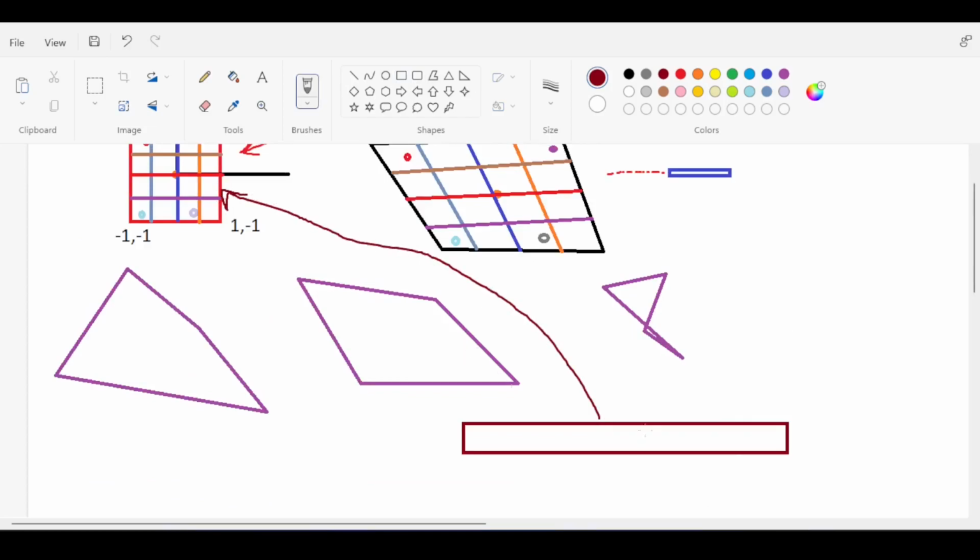Heavily modifying means that in one case you would just multiply by 2, for example. In another case you would divide by 5. This is a huge aspect ratio that doesn't work. Now, to deal with this issue, you would basically have to subdivide this into pieces that seem to be more friendly to the isoparametric element.